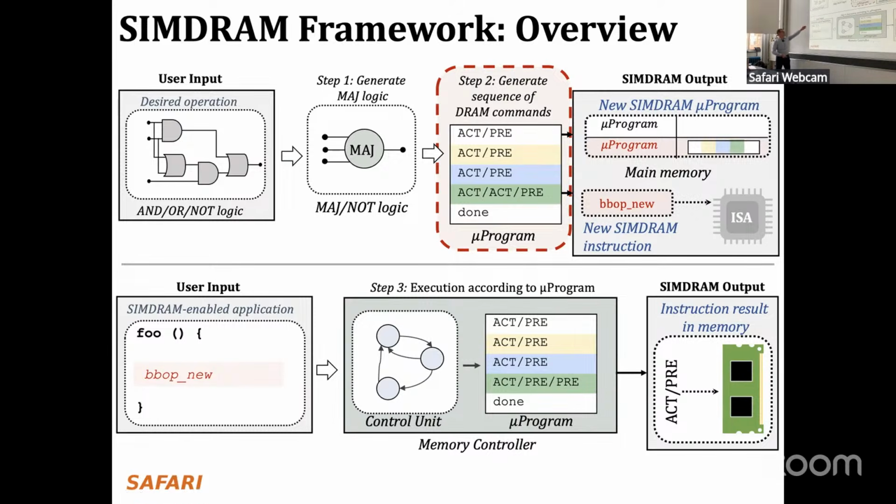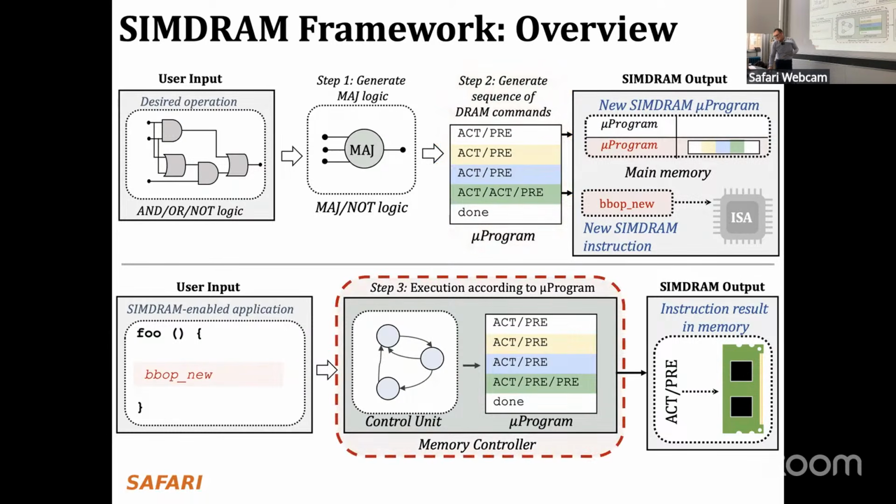You can still keep the sequential programming model that people are used to and add these operations that are executed on the memory side. Okay, this is an example of what we called PIM-enabled instructions in earlier work in 2015. This is a PIM-enabled instruction, and you can also decide where to execute it, right? That's another option. Okay, so that's the framework over here. This way, you can implement any operation as long as you specify an instruction corresponding to it, and as long as you have a microprogram that implements it in the memory controller.